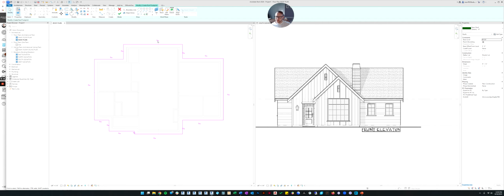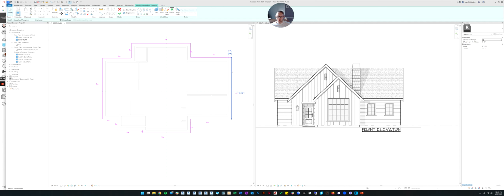So now you can see it automatically makes every single edge sloped. And that's not what we want. So if you remember, we're going to go through and try to find the edges that aren't sloped. So I think that edge, and then that edge, that edge, that edge, and that edge. In my mind, those are the ones that aren't sloped. So I selected all of those, and I'm going to come up here and uncheck Define Slope. Do you see how the little slope marker disappeared from those lines?